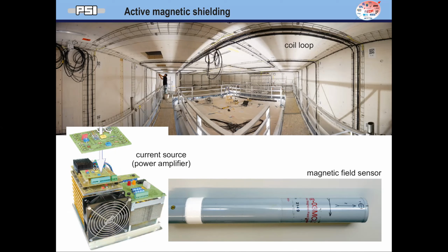On top of those are large power transistors, and they are then controlled by an operational amplifier. And the nice thing about those large amplifiers is, in principle, they act like one big operational amplifier, which can deliver, in this case, 15 amperes and 50 volts, so quite some power.